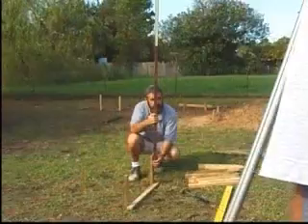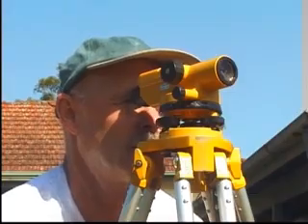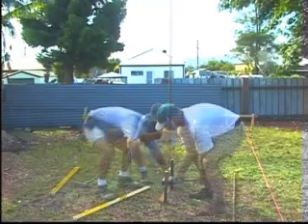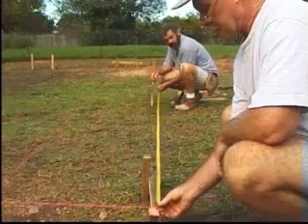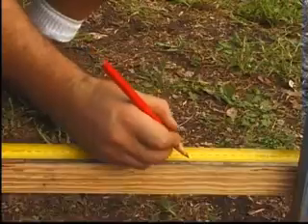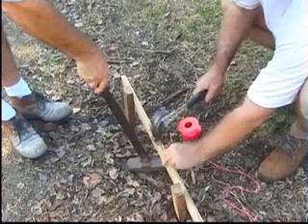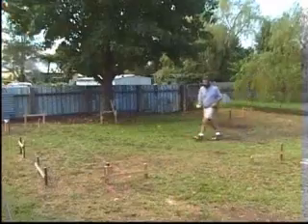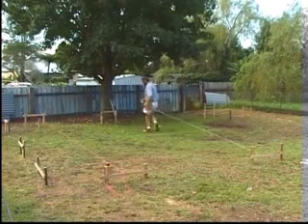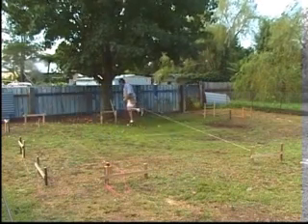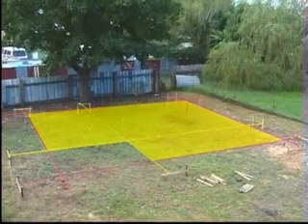These cutouts require additional profiles to be set up and levelled. Up 5, whoop. That's good. The new profiles are placed in line with the existing ones. Cutout measurements can then be made directly from ledger to ledger on profiles. String lines join these profiles to create the cutouts in the outline of the building. With all string lines in place, the external perimeter of the building is accurately defined in the one level plane.